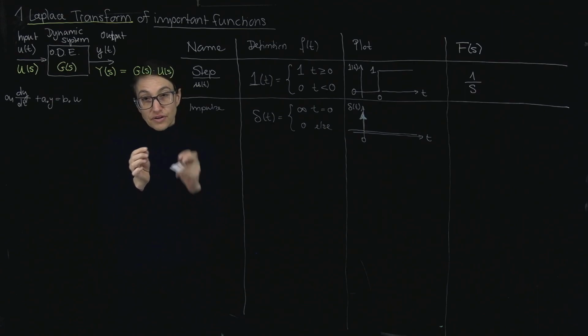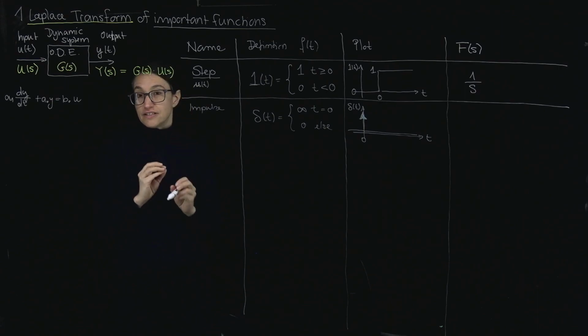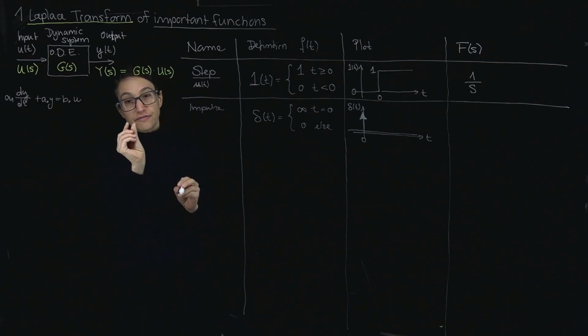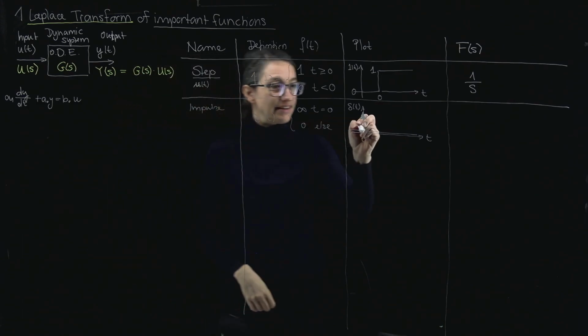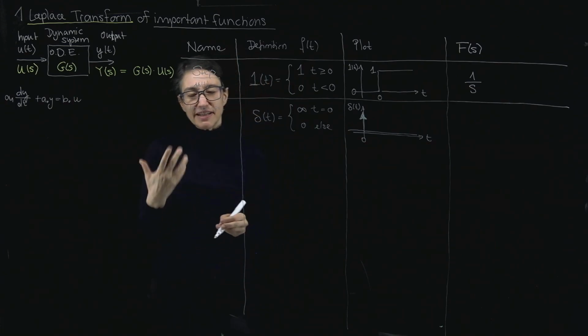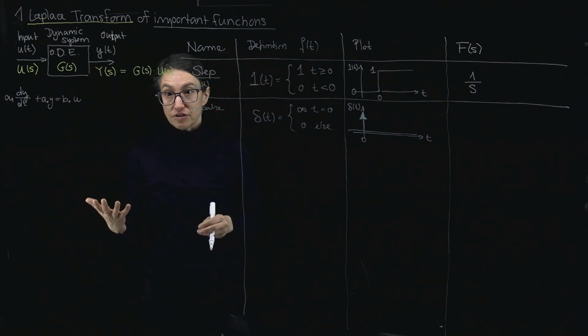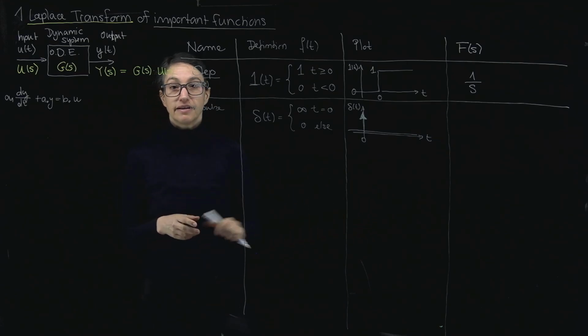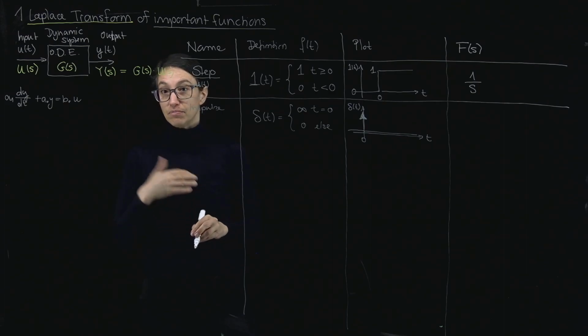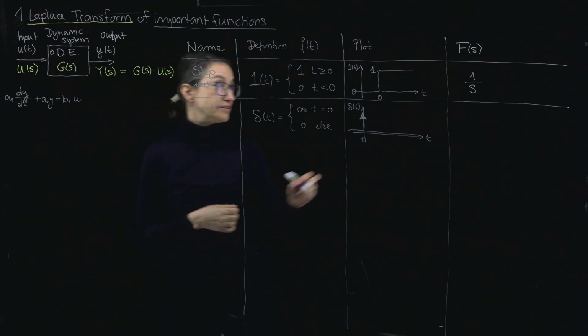It's not exactly an infinitely short period, but it's for a short period, and it looks like a little pulse here, but we pretend it's an impulse. And I want to know what's the impact on the concentration at the outflow of the tank. And this would be an example of a pulse, and we model this often with an impulse.